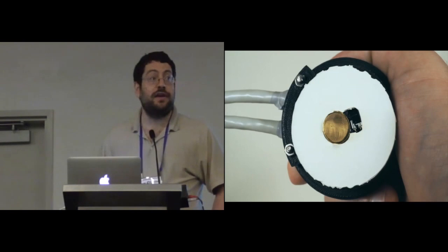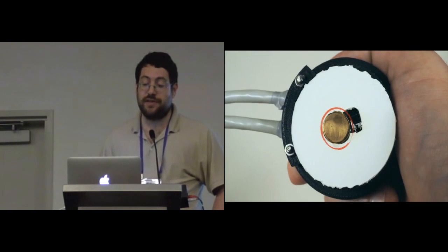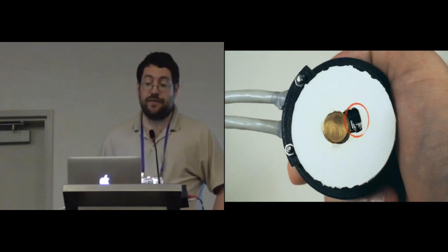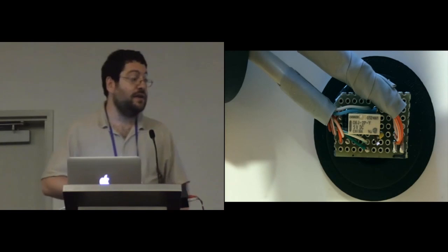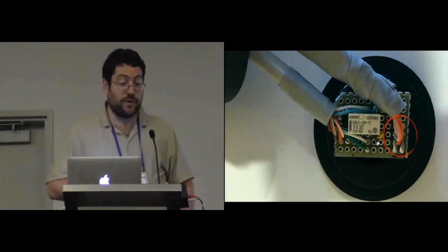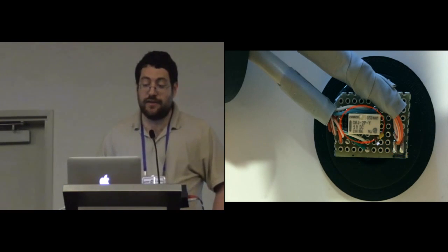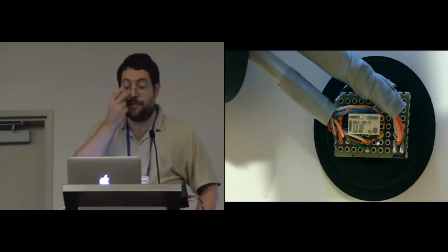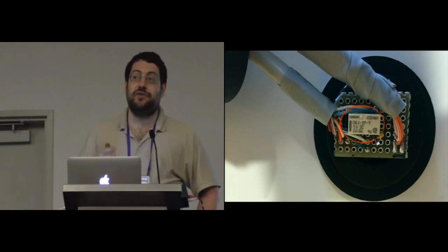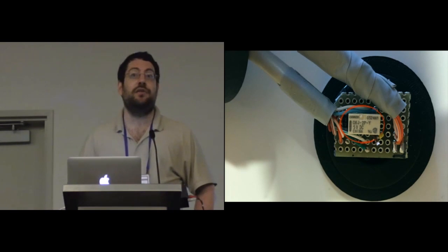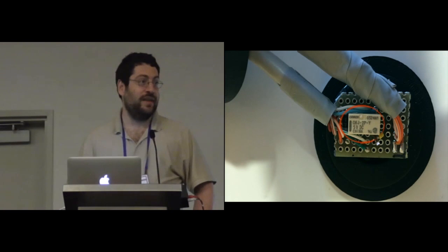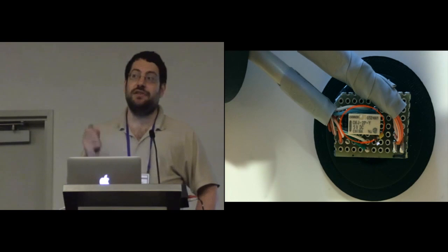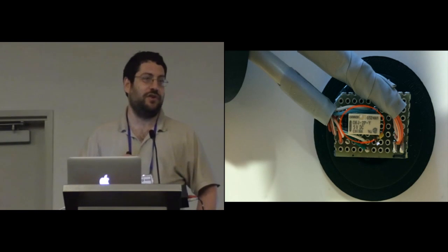Here's a picture of the underside of the measurement head. So we have the brass contact there, and we have the photodiode on that side. If we flip it over and take the cover off, this is what the inside looks like. There's the connection to the photodiode, and on this side is the switch. Now, we're using a mechanical relay as our switch because the change in capacitance needed to trigger a touch on a screen is incredibly low. It's in the femtofarad range. And almost all solid-state switches leak just a little bit of current through them even when they're turned off.